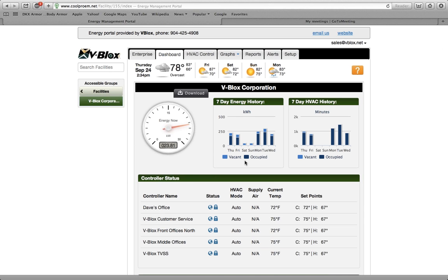So what we typically see in facilities like that is 3 to 4 hours of runtime on your air conditioning while you're closed on those weekdays, and then on the weekend between 12 and 15 hours of runtime. And that can be really substantial considering you're open 9 hours. So even if you're cooling, let's just say 60% of the time, because your air conditioners turn on and off.